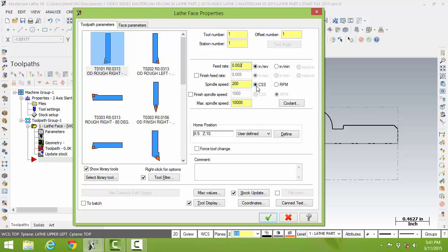And constant surface feed, we talked about it in class, where on the outside of the diameter, if it's 10 inches, no matter how fast it turns at that time, one revolution will remove a chip thickness of about 2/1000. So the finish will be constant. The surface feed is constant as it gets to the center, and as it gets smaller, it gets faster and faster and faster, but that chip load stays constant. Anyway, we will start out in this project with 1500 for the facing and the max. If you remember, the max is the G50. We don't want it to go over 2500.